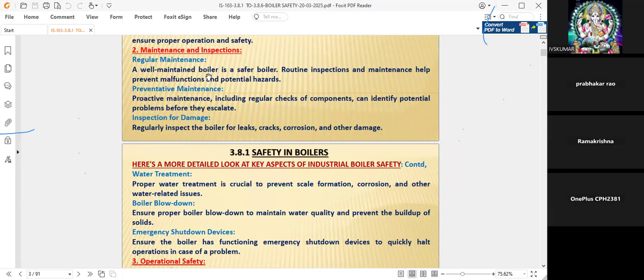If, after maintenance, any leakage is coming, management will not leave those people. That's why these dedicated people are working in a systematic manner, and they are experts in inspecting the boiler for leaks, cracks, corrosion, and other damage. If an opportunity comes and the shutdown time is sufficient, then only they will attend. Otherwise, they will simply do patchwork and inform the inspector of factories.